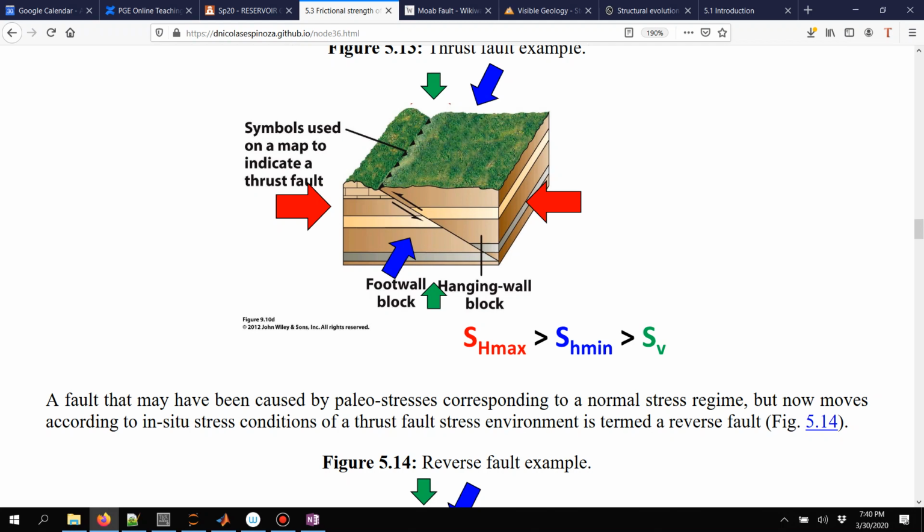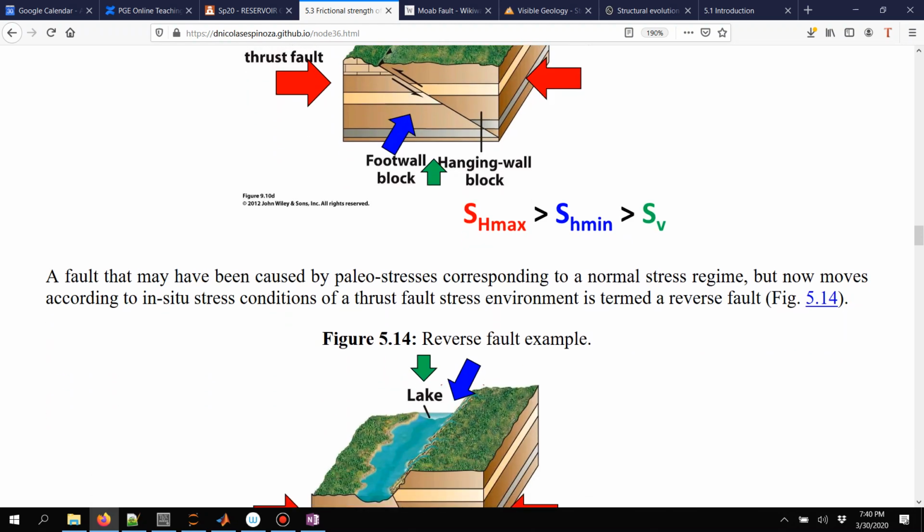If we go to a reverse fault, like this one, then now this fault is created by the horizontal stress, which is significantly higher than the vertical stress. And when that overcomes a ratio of sigma 1 divided by sigma 3 higher than Q, that's when we have a fault slip or a creation of a new fault. And again, I'm going to explain why we have this orientation in the next topic, and this would be, in this case, the case of the thrust fault.